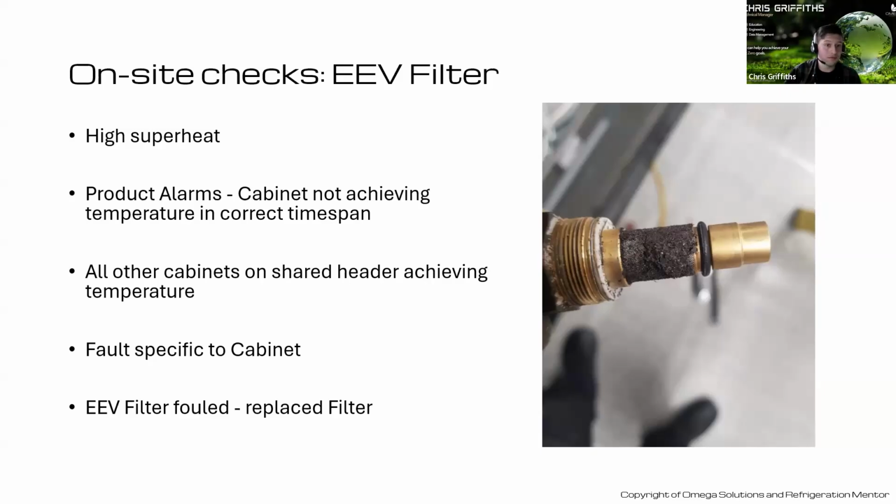So again, I presume, John, you go through, check everything over, strip the valve apart, and find that. That's a pretty obvious cause there. You'd see that step change on your trend with the valve gradually opening more, as Trevor pointed out earlier. It's a good feature to have, without a doubt. Yeah, I think so too, because there are some valves out there that don't have filters before it. And I think most of the manufacturers today do at this point.